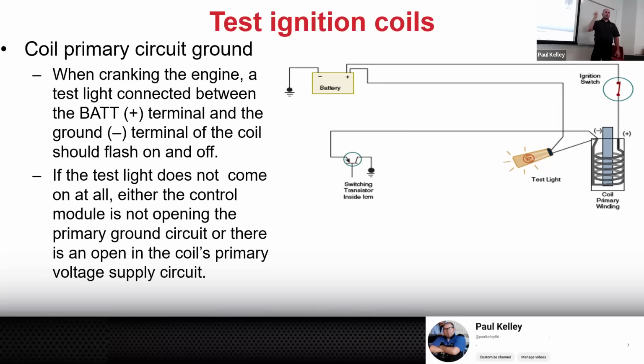Cool. So I go down there with one tool, the test light. I put it on there and I say, "One, start it." And I look, and what should I see? Flashing. Exactly. Flashing, because the triggering device should give ground and take it away, give ground and take away, give ground, take away.